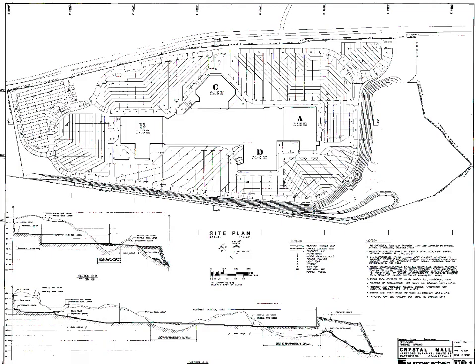Okay, now we're back to thinking about a large site plan, and I briefly want to talk about parking, since parking is what drives everything in a lot of the current developments we do. You can see the huge area of parking surrounding this building. And the usual ratio for something like retail will be about 3 parking spaces for every 1,000 square feet of retail area. And you'll go out to areas and see these parking lots are empty all the time.